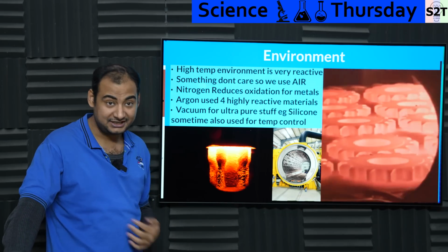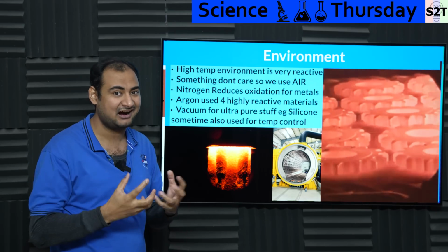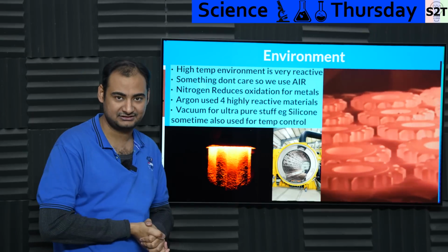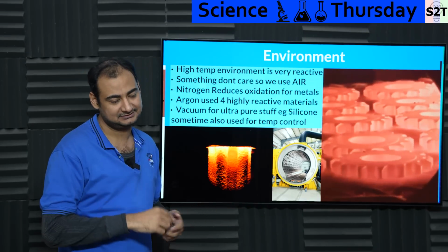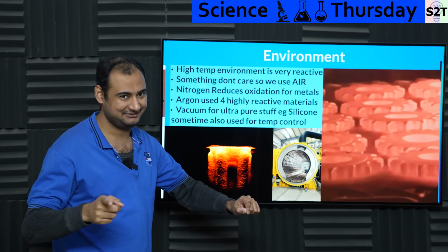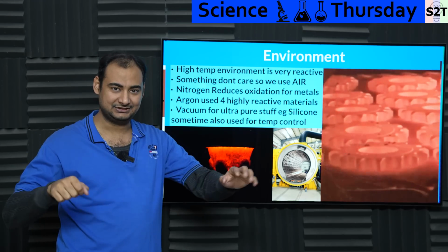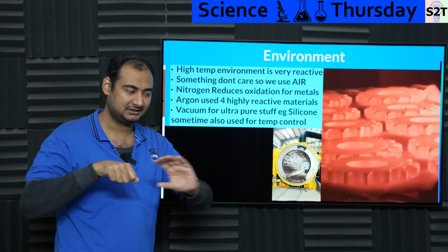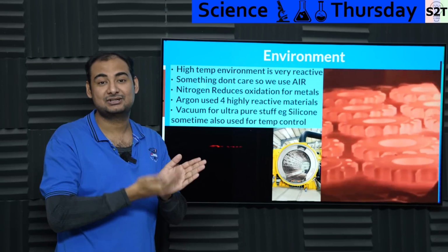You have to basically put in nitrogen or carbon. You may want to infuse carbon on the surface, so it becomes very hard. It has softness of the core in the back end, and it becomes hard on the surface, almost like a katana. Katana is very well known because it's a bimetallic blade. Now, like, okay, wait, it's made out of one thing. They temper it differently. If you look at the edge part, it's very shiny, very hard, so they edge it. But you look at the back wavy pattern, basically when they are forging it, tempering it, they put clay and then they put it in a furnace. So the back end does not get hardened.